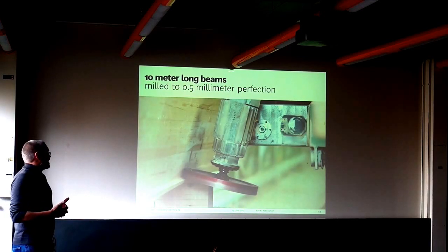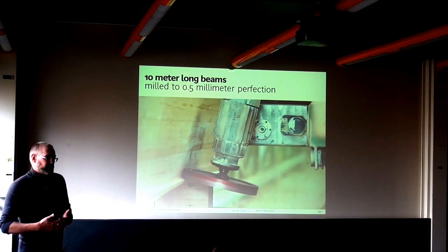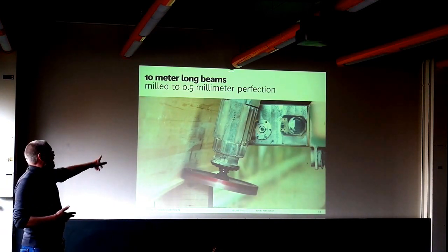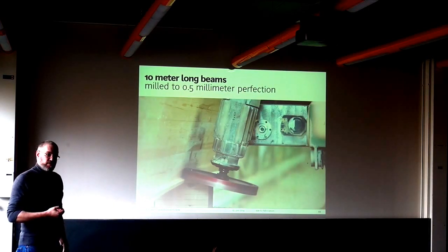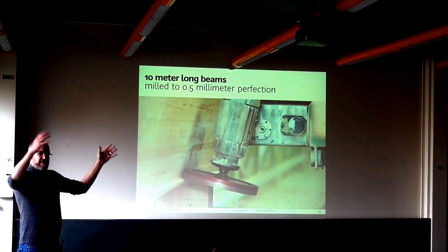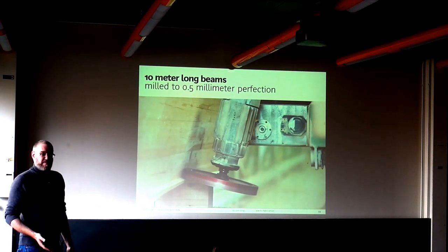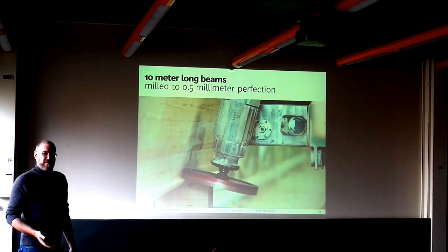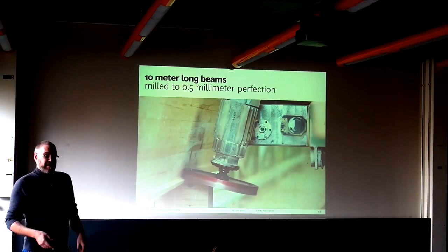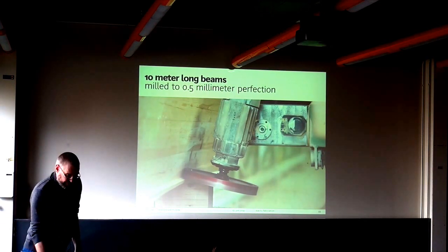And this is, I think, in the SIA norm, about 3 or 4/10 of a millimeter. Yeah, so you need this precision to get the connections right in the end, which means you have to provide fabrication data that's precise within 1/10 of a millimeter. So if you're taking the input from an architect or engineer to feed into your parametric model, even that has to be precise to 1/10 of a millimeter, because after that, the errors just multiply. You never get the information back once you threw it away.